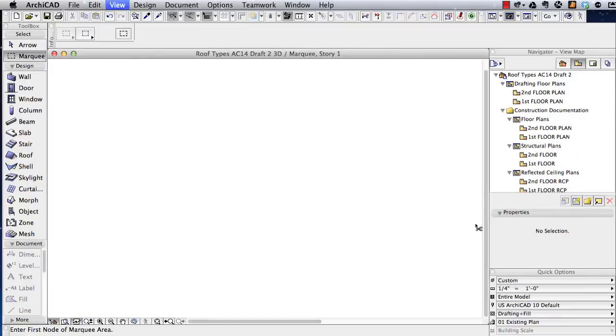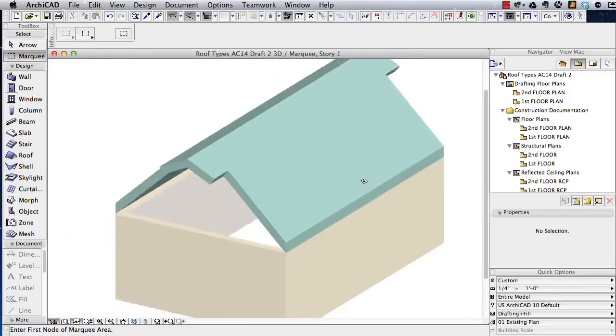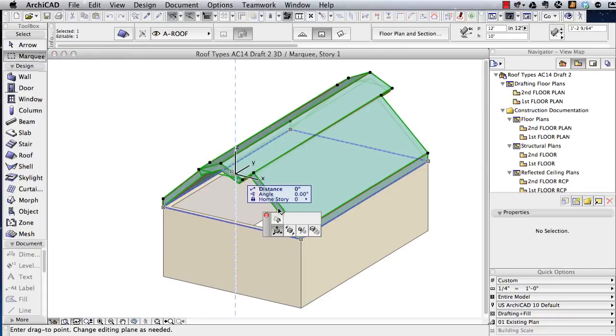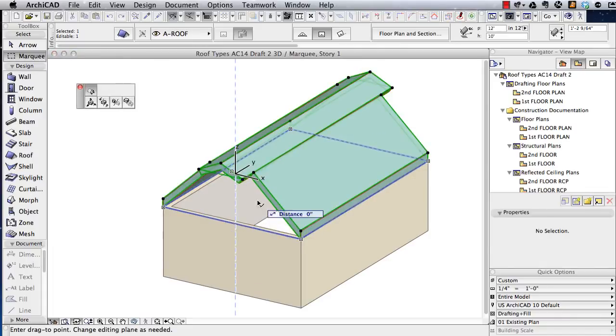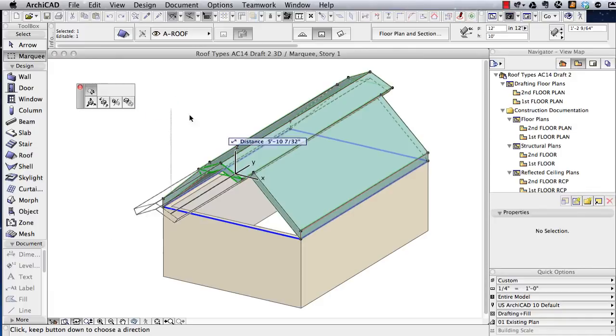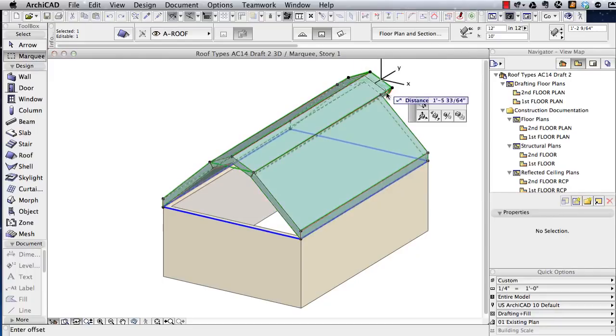This is why training and experimentation will get you prepared for these things. So the little overhang here is controlled by that edge, this option here to reposition. It's called the Gable overhang here, so I can just snap that into position. So that part is easily addressed.